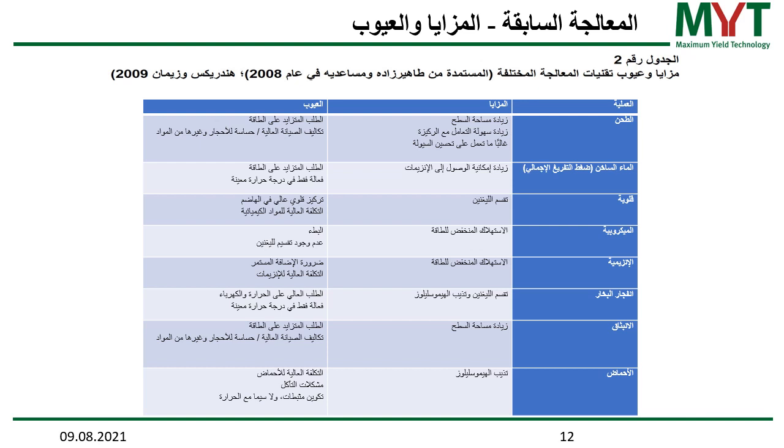Steam explosion is a combination of heat and pressure, and then the release of the pressure in a very abrupt way. So you open up the vessel quickly and then you have a high pressure drop. This breaks down lignin and solubilizes a lot of the fractions within the substrate. However, you have heat and electricity demand, and so you really have to check if the effect compensates the costs and the energy demand.